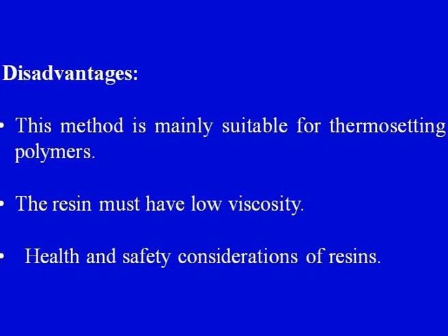And finally a pressure would be applied with the help of a top plate of the mold, and after room temperature curing we will get a composite laminate. So the process is fairly simple. The disadvantages are the method is mainly suitable for thermosetting polymers, not very suitable for thermoplastics.